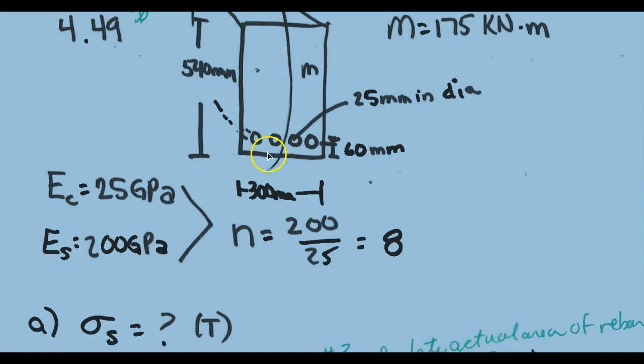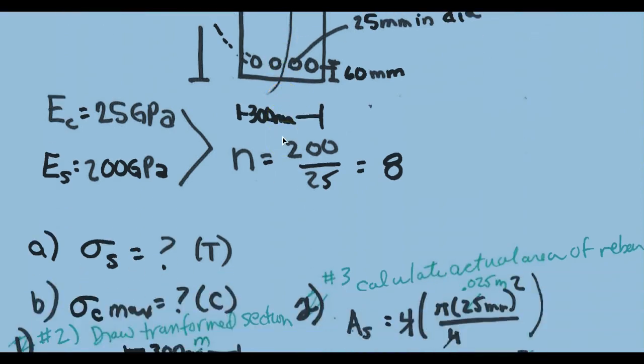And this is the only configuration that works for reinforced concrete, because the steel is embedded in the concrete in order to make the concrete bear tension, which, as we talked about in class, concrete is very poor in tension, so really everything below the neutral axis of the transformed section of this concrete will not do anything except for hold that rebar in place.